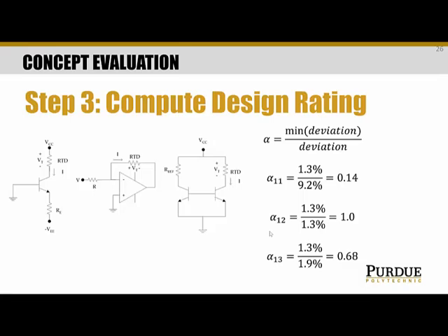So I'm going to give one example. In the case of the temperature monitoring device, accuracy is one of the criteria that we identified in the previous step. And so how are we going to identify accuracy of the circuit? Well, what we decided to do here was evaluate the circuits according to a SPICE analysis with 10% resistors. So what we did is we measured the deviation in the output voltage, meaning that we measured the change from the nominal voltage from the 3 different designs.